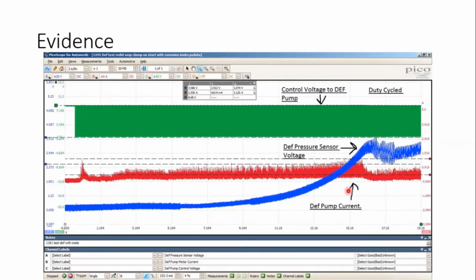And the opposite of that, when it starts to have pressure where it's dropping down, or your duty cycle is not grounded on as long, it makes the pressure drop, and it also makes your pump motor current go down, and it also makes the RPM of that pump increase, okay? So this is how it's controlled.